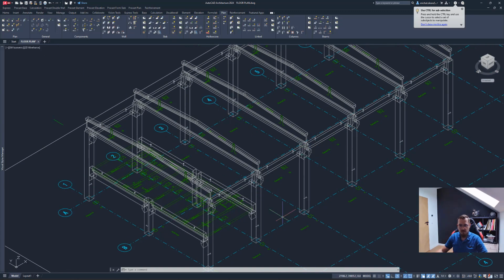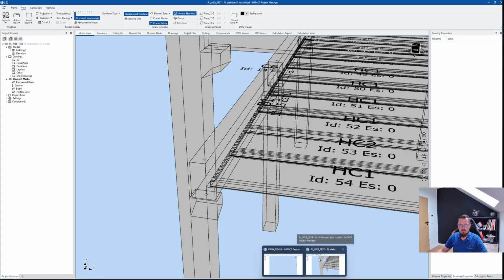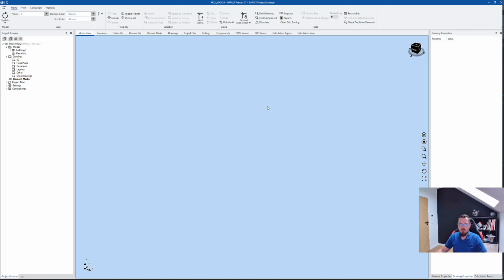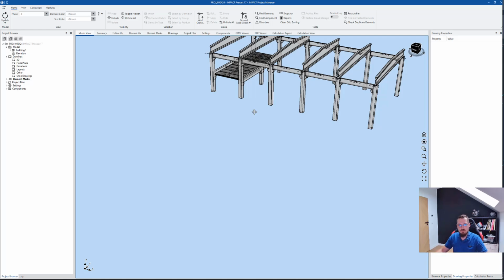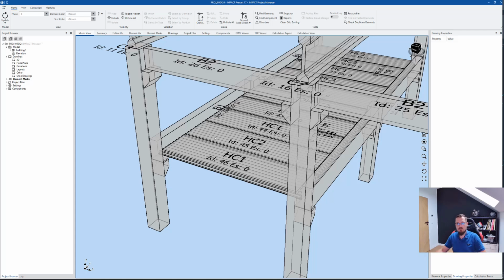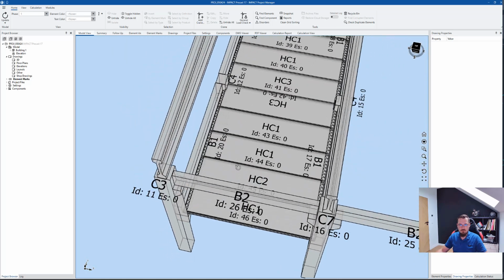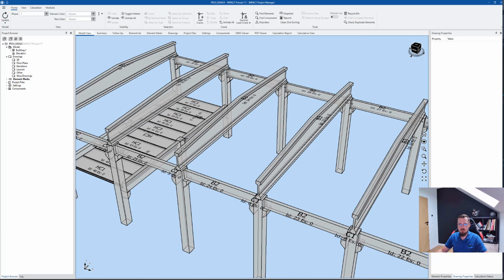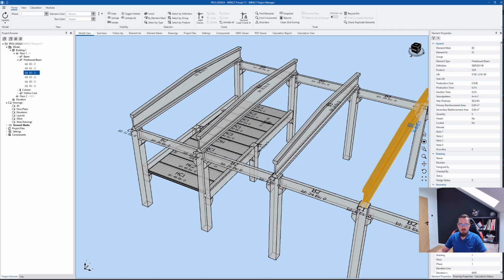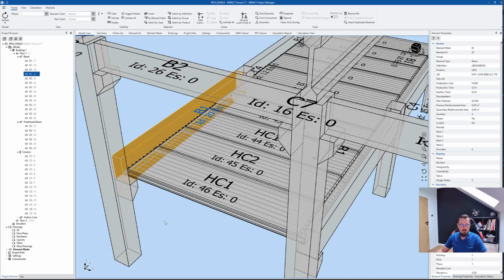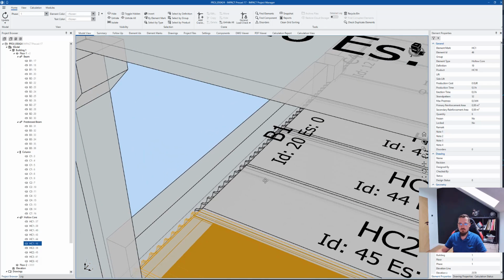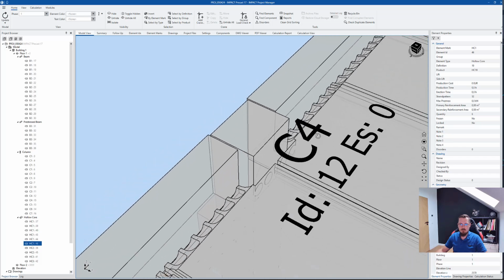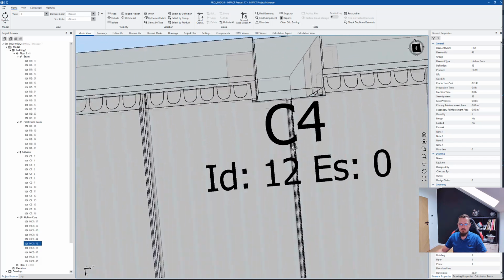With everything being saved, I can go ahead to Project Manager, and that's this one for my project now. And I just need to refresh or rather update the model. So the database updates with all the elements that we've created, and like so, it loads up the elements. So those are all beams, columns, and hollow core slabs that we've created. You can see we have the ledge elements, we have the columns with corbels, we have the ledge beams as well, and we also have hollow core slabs. And as you can see, we can even see the fine detail on the edge that we've created. If we go over there, we also see the cutout around the column that we have.